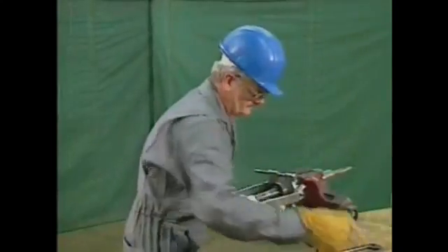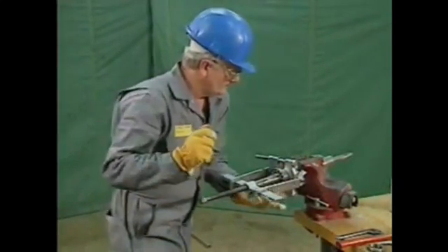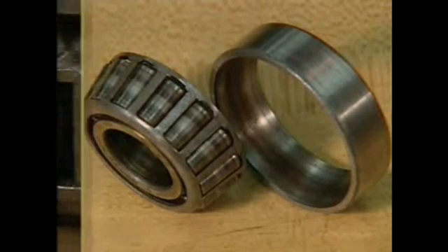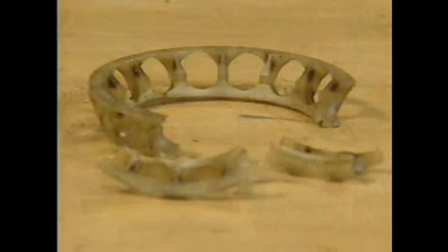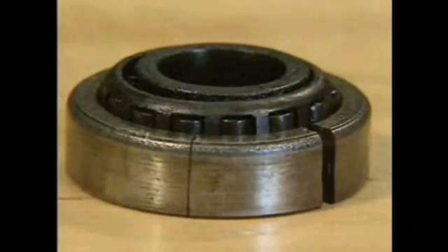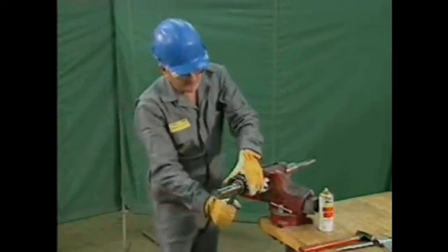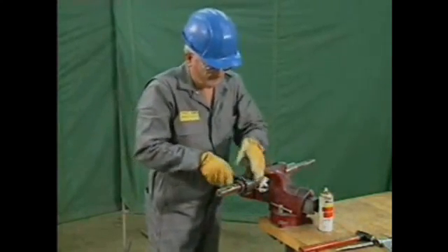After a failed bearing has been removed and taken apart, other evidence of bearing failure may be seen. This evidence may include burn marks, which are blue or brown marks on the rolling elements or the rings, spalled areas, which are places where the surface of the metal has flaked away, a bent or broken retainer, cracks in the rings, and discolored lubricant. If the bearing failure is unusually severe, all of these signs could be present, but not all of the signs are necessarily present with each type of failure.